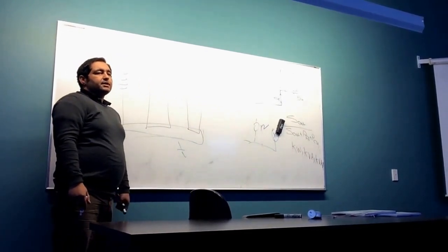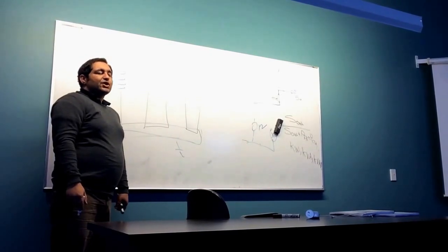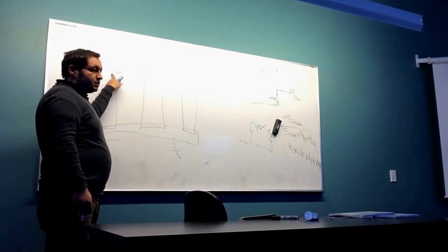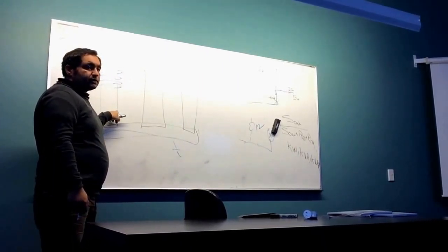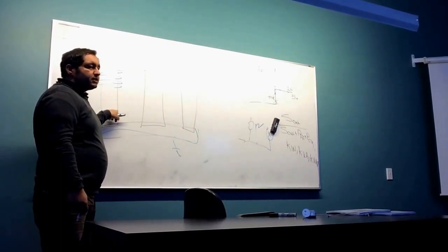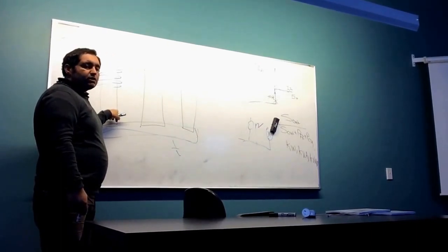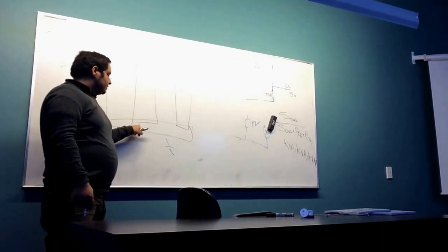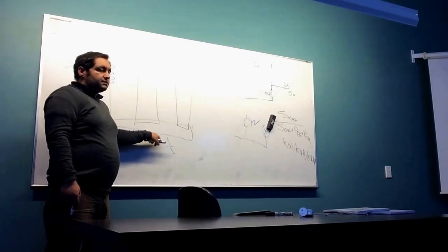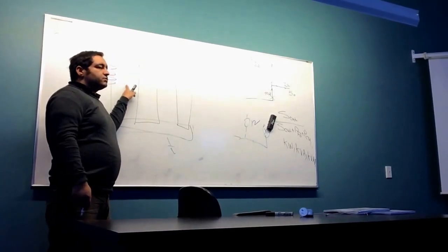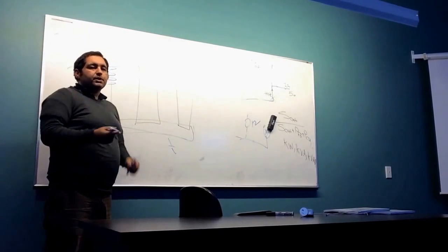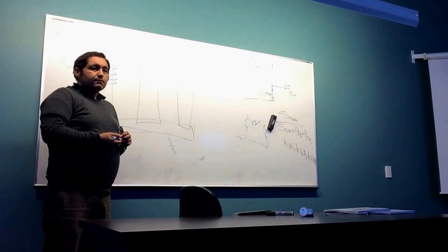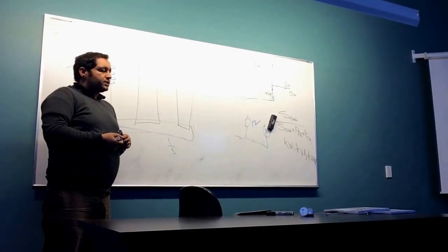So what's happening, it is better to keep the one that has higher voltage a little bit on top compared to the one that has lower voltage. This lower voltage requires less insulation, isn't it? So it's all about safety. Lower voltage needs to be insulated too, but less than higher voltage. So it's better to keep the higher voltage on top compared to lower voltage. Okay? Any other thing that you guys wanted me to explain?